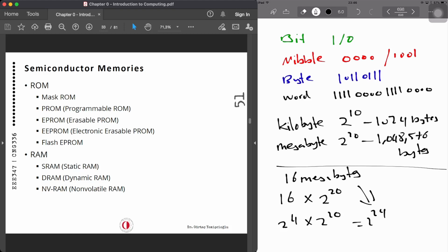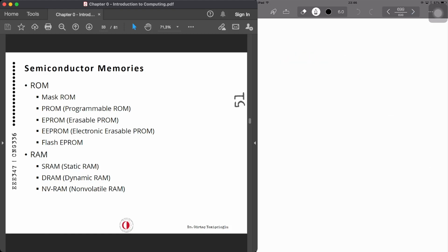Right, so let's get into the memory organization and let's see what types of devices or memories we can have. Now, the number of bits that each location within the memory chip can hold is always equal to the number of data pins on the chip. This is important. And how many locations exist inside a memory chip? That totally depends on the number of address pins.